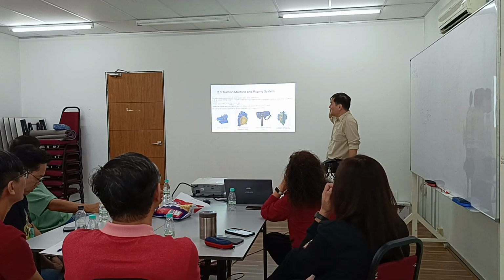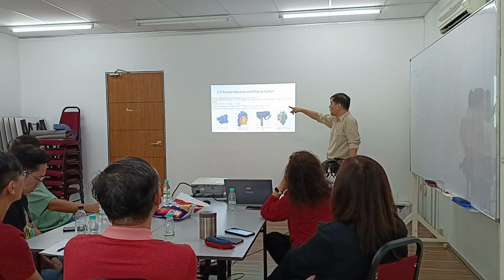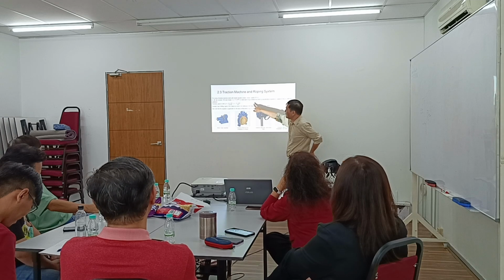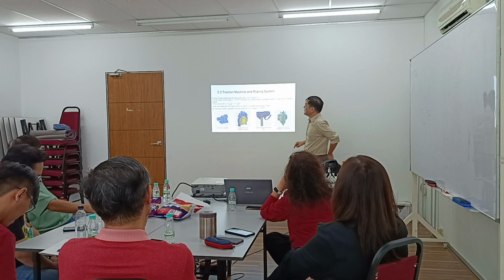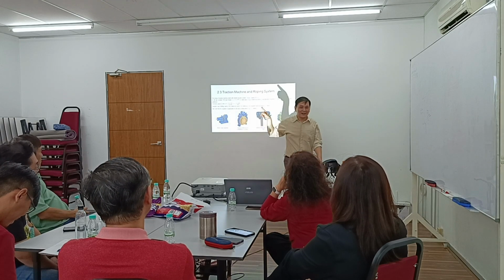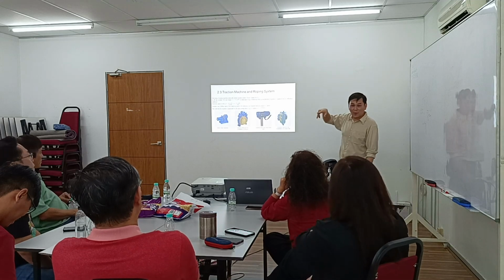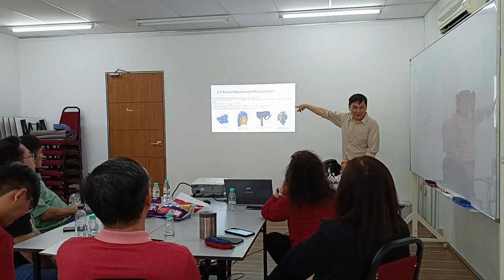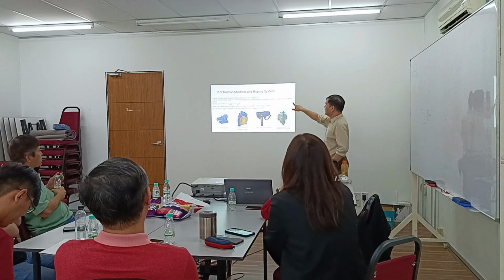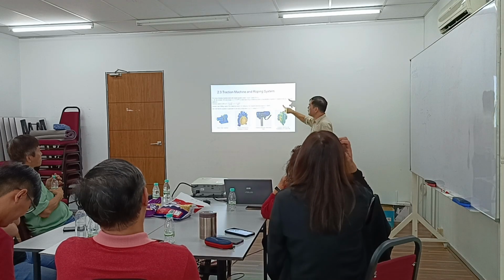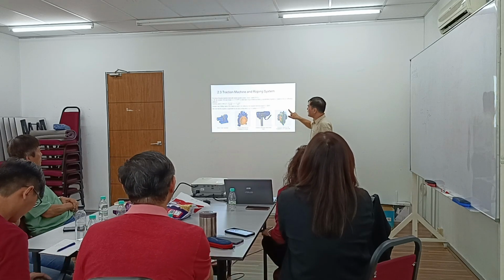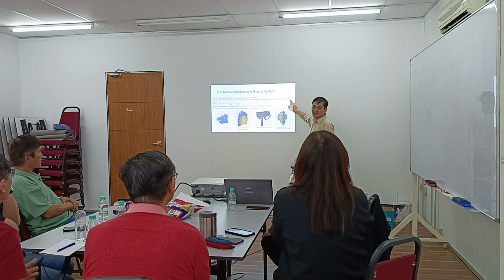So this is a traction machine, also very important. So the sizing of the traction machine, so this is a little bit of physics. So the sizing of the power is force times speed. So if let's say we consider 10% margin, still remember just like I mentioned, the overweight 10% margin is actually from here. So the rated load, balancing factor, gravity, speed, efficiency coefficient. So the keyword of the motor power size is here, efficiency.